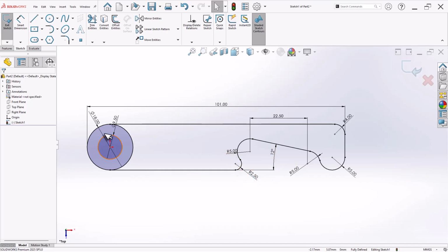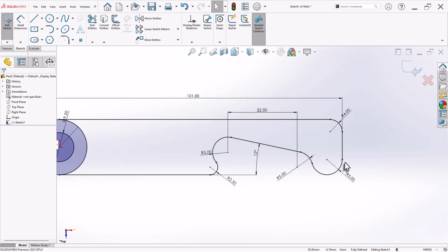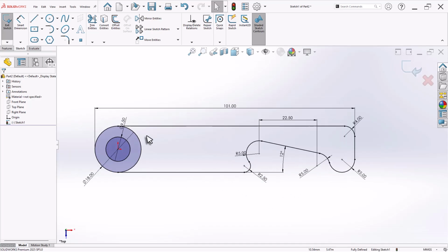Now it is okay. So if you have any problem in these regions, make sure you do it correctly. You can go one by one. Just create this segment and give the dimension, give this segment the dimension, draw the line, create the arc, give the dimensions to this line and center line, and lastly you draw this arc. So as per the sketch, you should have this radii on the left side, and make sure it is tangent over here, and this line is tangent to this arc.